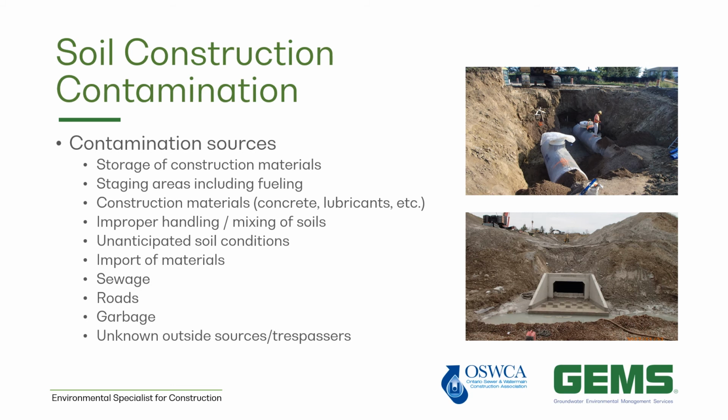Other construction materials, including the actual concrete, so stormwater culverts, anything that would have concrete material, can add contamination to your site, as well as any lubricants or gasoline, whatever you might be using on your equipment for repairs or fueling. Improper handling or mixing of soils on site. If you have some contaminated and some clean and they happen to get mixed together, that can create larger issues that you then need to deal with.